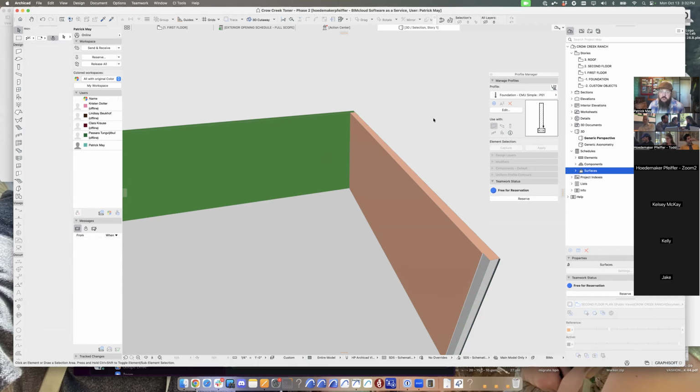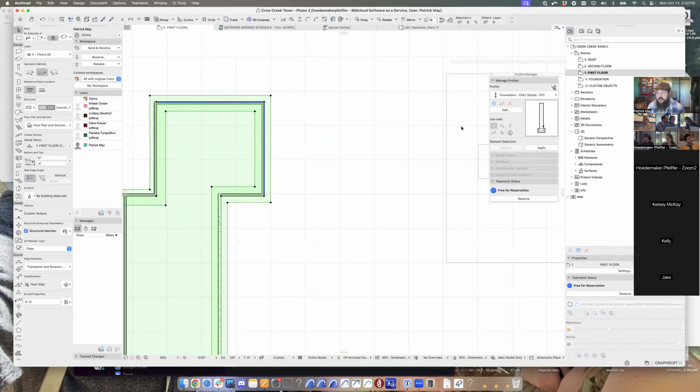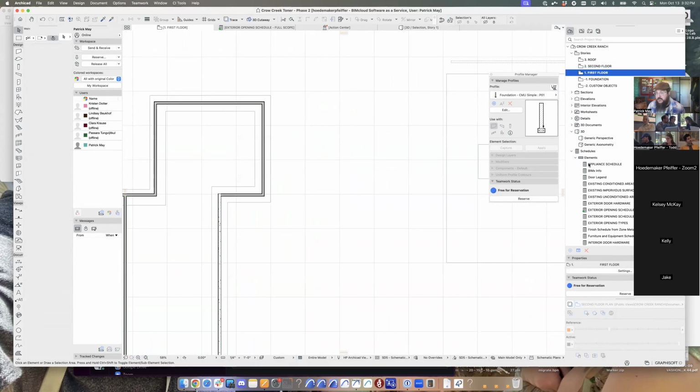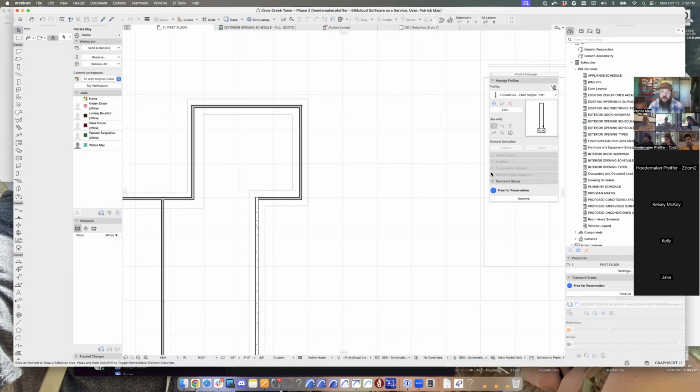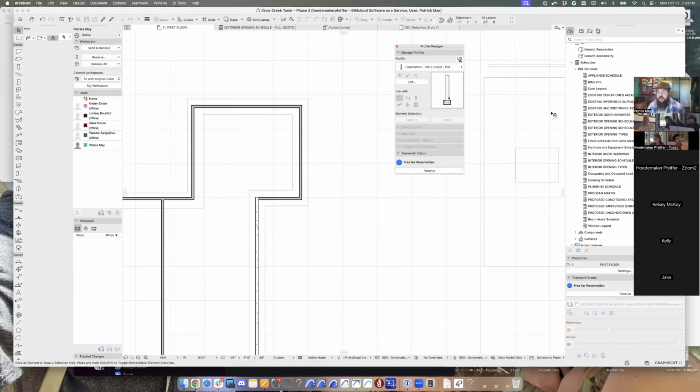So usually what I do, because I don't like the Excel option either, is I create an element schedule that lists just all of my rooms. And then the finishes or the materials of those rooms are manually input as schedule fields. Could we be doing that versus getting away from Excel? I think that it's a better solution than scheduling in Excel, yeah. Okay. I mean, it's still not great. No, it's not. It's still not automated.